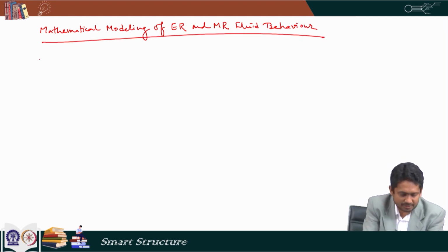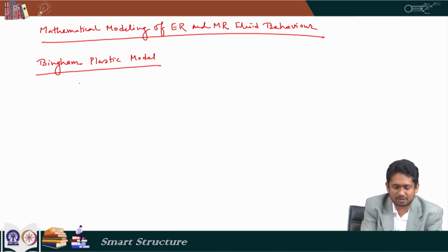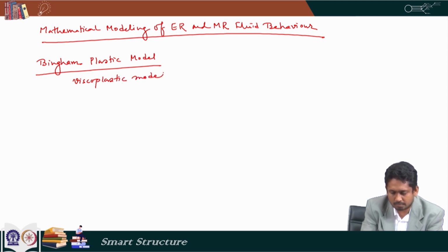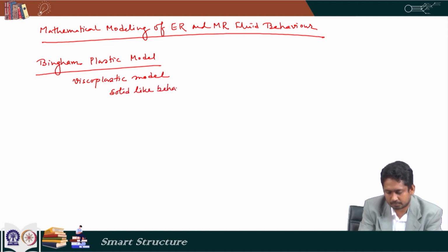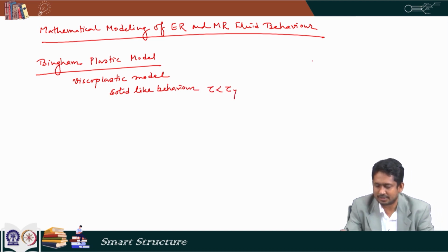The first one is the Bingham plastic model. This model is a viscoplastic model. It shows solid-like behavior when tau is less than tau y.